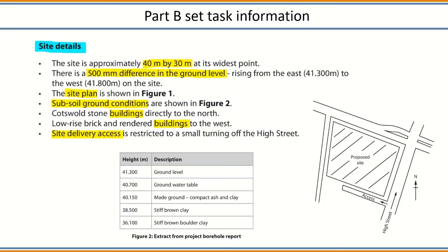It can also affect the foundation of the building. The concrete could be damaged by sulfates. The borehole report is also telling us at what depth a firm bed is found for the foundations to be constructed, and in this case, the firm soil will be approximately 5 meters below ground level. The best option for this situation will be pile foundation.